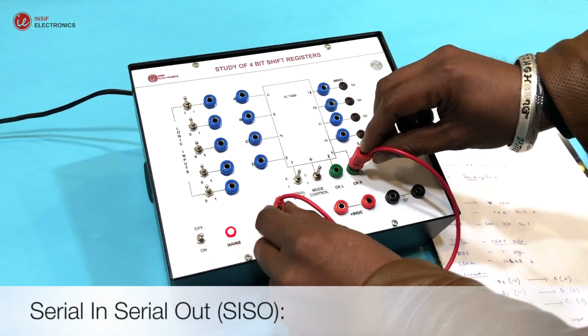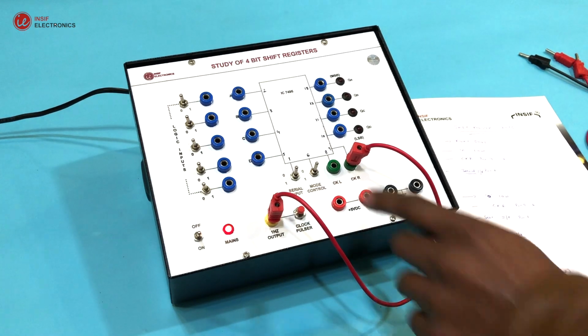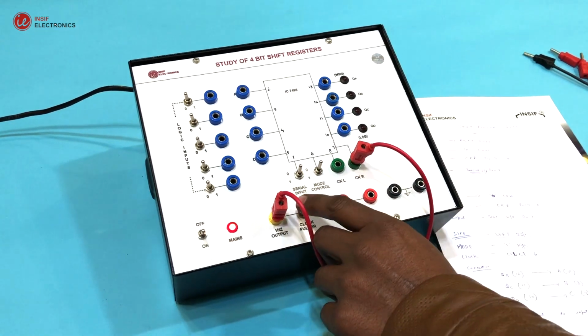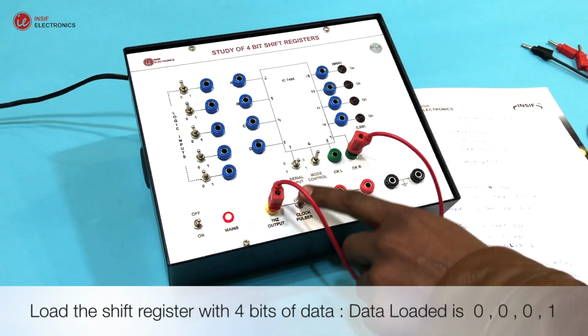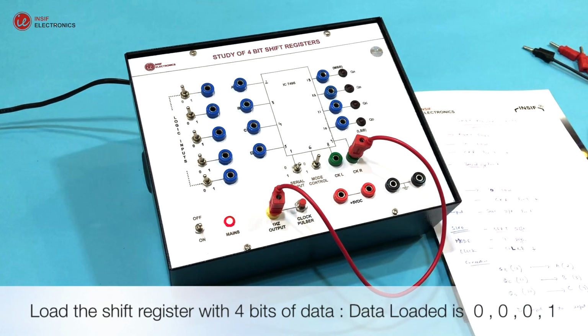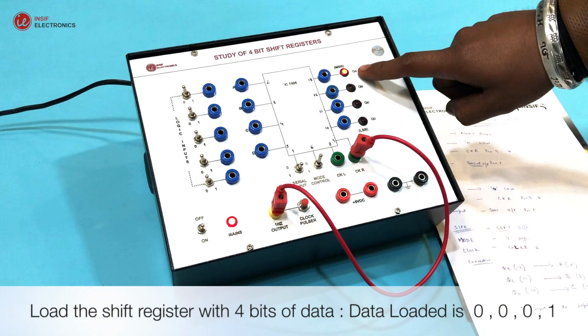Let's perform serial in, serial out. Set mode to low, that is logic 0. Load the shift register with 4 bits of data, one by one serially. Data loaded is 0, 0, 0, 1.